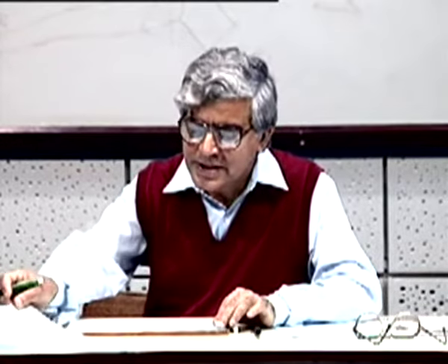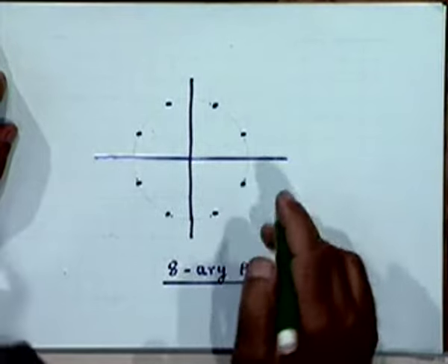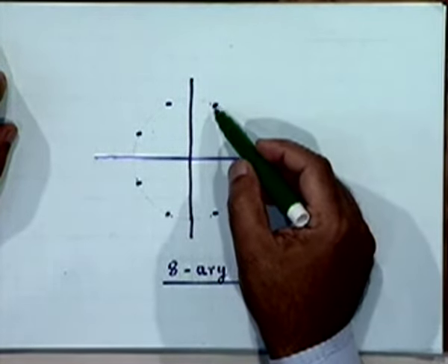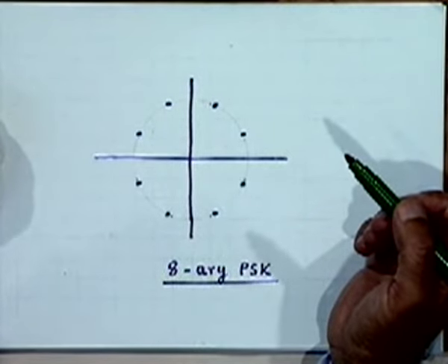However, there is no necessity to think of a general quadrature amplitude modulation in this particular way, right? You can basically choose any set of points on a complex plane and associate a certain number of bits representing that point, right, to be represented by this point.